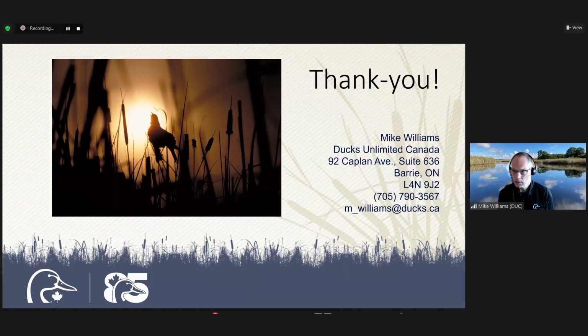Yeah, sure. Again, because we don't expect a lot of sediment entering into these systems, we expect them to last the full lifespan of that 50-year phase during the operation of the site. And another great thing about the naturalized systems is that there's not a lot of hard engineered structures to remove, no concrete, that type of stuff. So basically if you pull the control structure out, when you're done, the site will naturalize quite nicely on its own. The cattail beds would likely just spread out. So there wouldn't be a lot of cost to decommission or naturalize the sites.